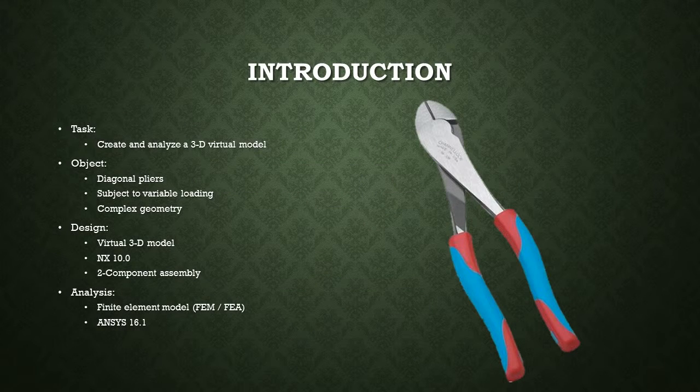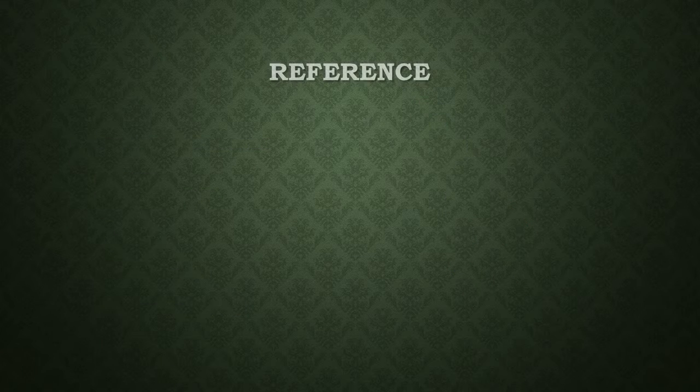We were tasked with creating and analyzing a 3D virtual model, so we chose a set of diagonal pliers. We chose these because they're subject to a wide range of everyday shop use. They also undergo variable loading and have a complex enough geometry that doing an analysis such as this would be worth our time and effort. We used NX to model it and imported it into ANSYS for our finite element analysis.